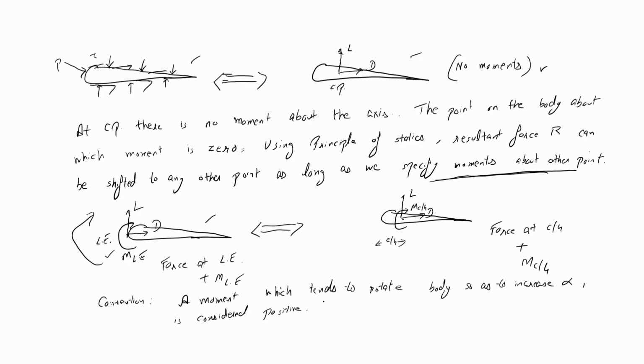Alright, so I am considering here the pitching moment. Pitching moment is nothing but the up and down movement of the nose. Okay, so here in the figure the moment shown here is actually positive. This is positive, it is pitching the nose upward. But generally speaking, for cambered airfoils, we have negative pitching moment. Alright, so the moment is actually negative